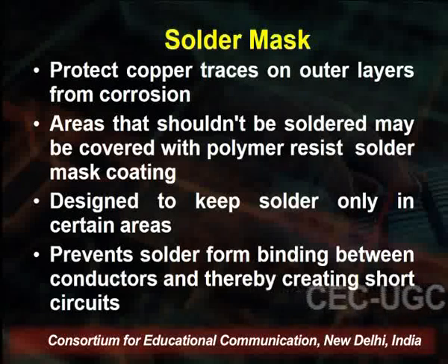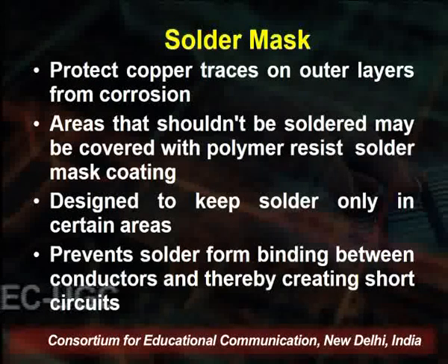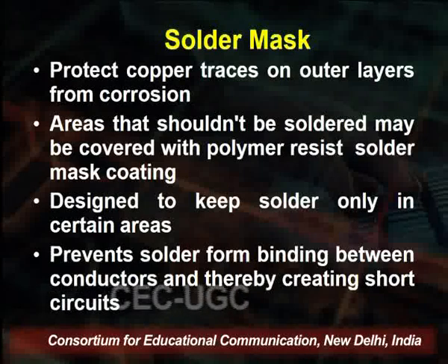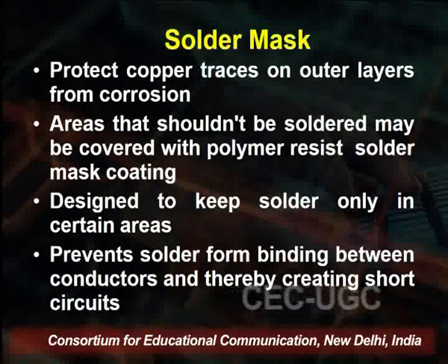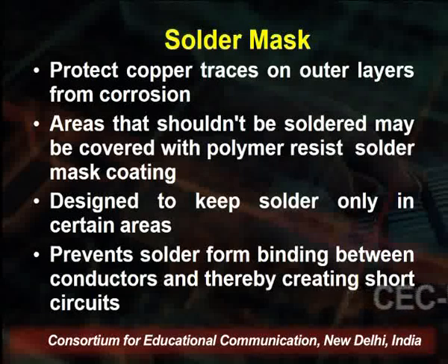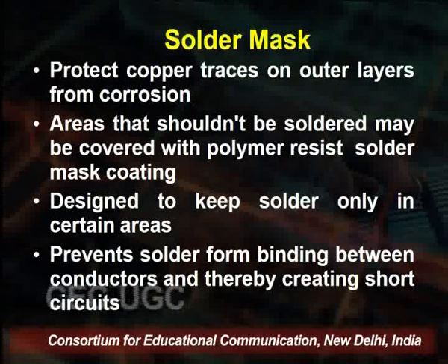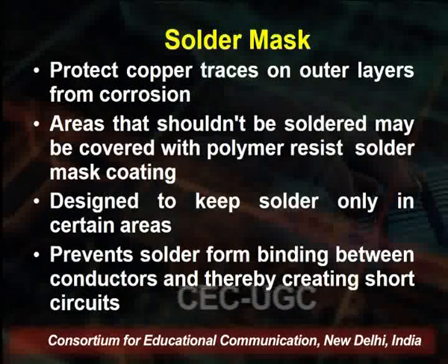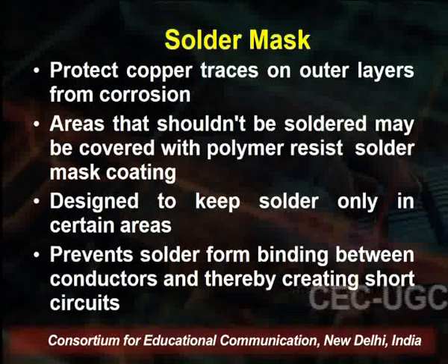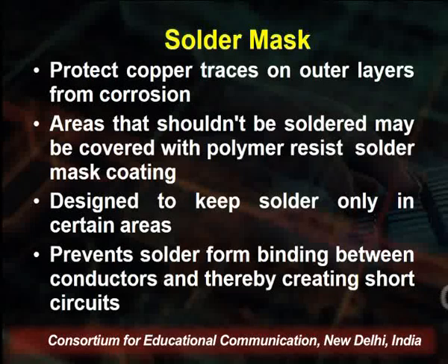An area that should not be soldered may be covered with a polymer resist solder mask coating, designed to keep the solder only in certain areas so that it can be done accordingly. So it prevents solder from bridging between the conductors, which can create a short circuit.